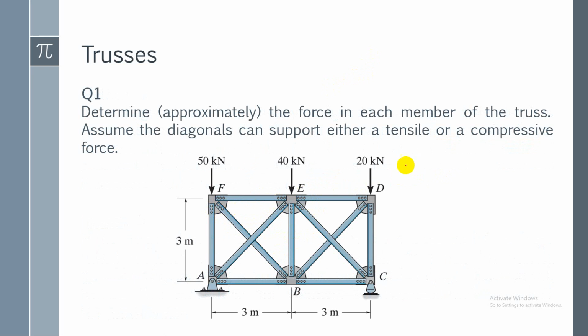So if you look at, let me see, say here, if you look at this one, how many members are here? So 1, 2, 3, 4, 5, 6, and 2 inside and 2 inside. So 6 plus 4, 10. And the reactions are 2 here, 1 here, 3. Joints: R equal to 3 and 3, 6. So M plus R greater than 2J. So this truss is a statically indeterminate truss.